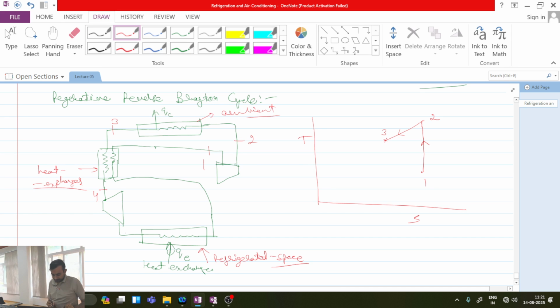heat exchanger, which is used in the refrigerator, is point 6, and this point is having low pressure because this point is after the expansion through the turbine. Okay, so of course point 6 will be having low temperature in comparison to the temperature of point 3. All are agreeing to this point? Point 6 will be having temperature lower in comparison to temperature of point 3.